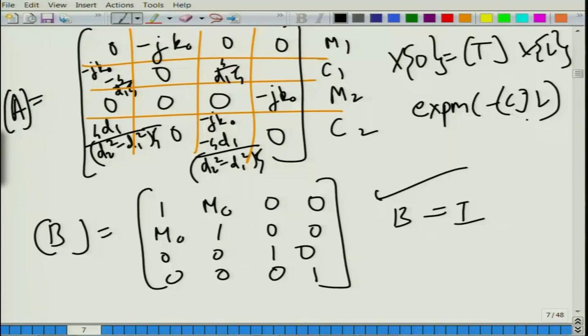It just becomes all the more easy. Once we know the overlapping perforate length L, the diameter of the perforate pipe and the annular cavity d2, and the frequency at which we are solving the particular perforate model, we can easily put in the expressions and go about doing that.